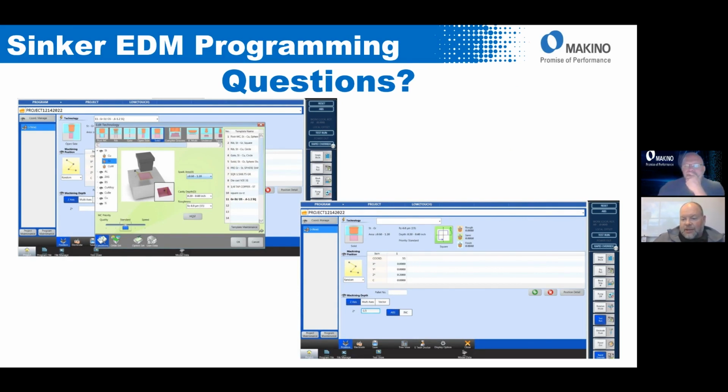So what is Super Spark? When I went through the Makino technology, the proprietary technology to the Makino control, I checked a box called Super Spark. If you notice, next to Super Spark there was a draft angle box as well. Super Spark is a technology that takes advantage of the draft that we normally put on electrodes anyway on the mold work side.